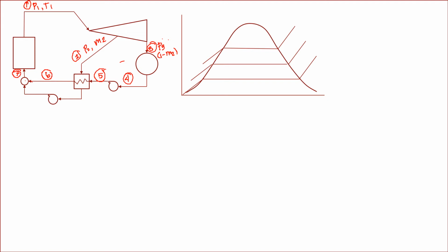And at this junction, where we have the output of this 7, the mass is now unity, because M2, okay, goes inside the closed feed water heater. It is at saturated liquid at 0.8, and it is being pumped to a certain pressure, equalizing with 0.7, 0.6, and 0.1. So this is your 9. Okay?